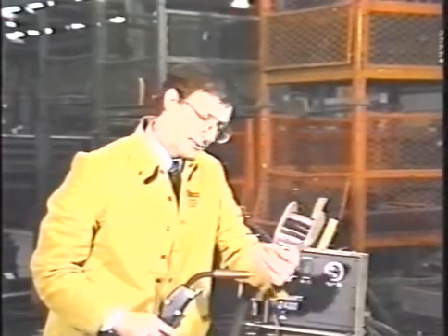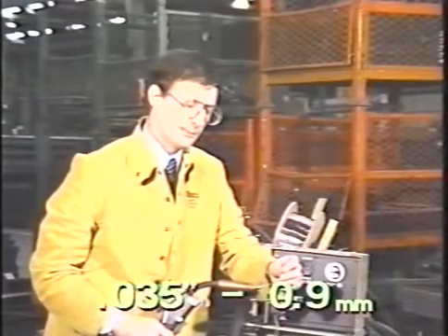In this highly competitive industry, everybody tries to find a way to save a dollar. If you use spray transfer on 1/8 to any thickness in the flat and horizontal positions, then you can save some money by selecting an 045 wire instead of an 035 wire.